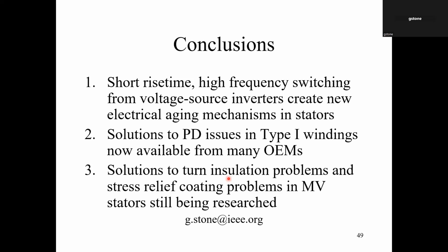And in the case of the form-wound windings, the issues have been turn insulation, but more importantly, the stress relief coating insulation problem. I think there's still some way to go on solving all the stress relief coating issues that can occur in medium voltage stators in medium voltage machines, especially as the rise times are going to get shorter and shorter.